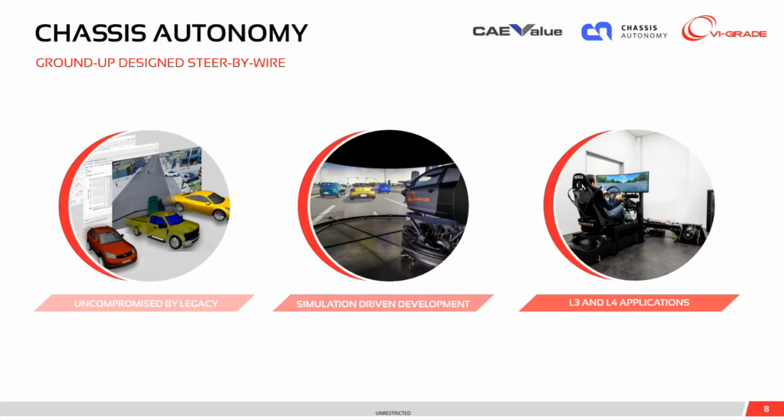We're called Chassis Autonomy because our original concept was developed again for autonomous vehicles. So we're looking into vehicles which have requirements for 1 million kilometers rather than conventional 300,000. We're looking at potentially heavy vehicles, 5-ton people shuttles, 25 kilonewtons rather than 18 to 20 for conventional passenger vehicles. So that's our primary market, but we've also got a lot of activity, a number of projects ongoing to develop for level 3. So that's when we're looking into human-driven steer-by-wire, as we call it.